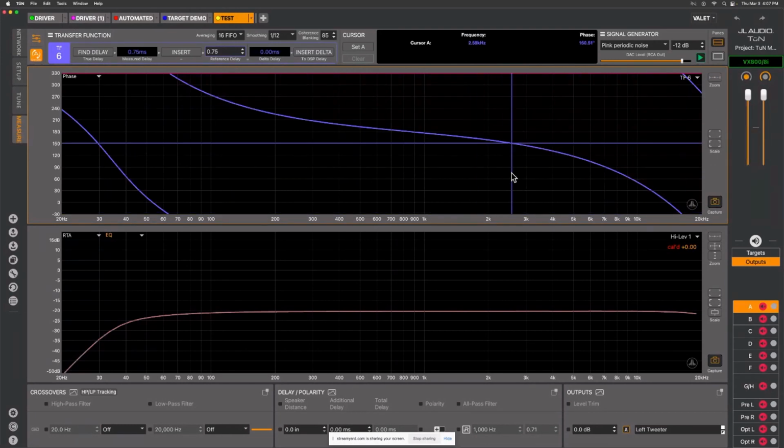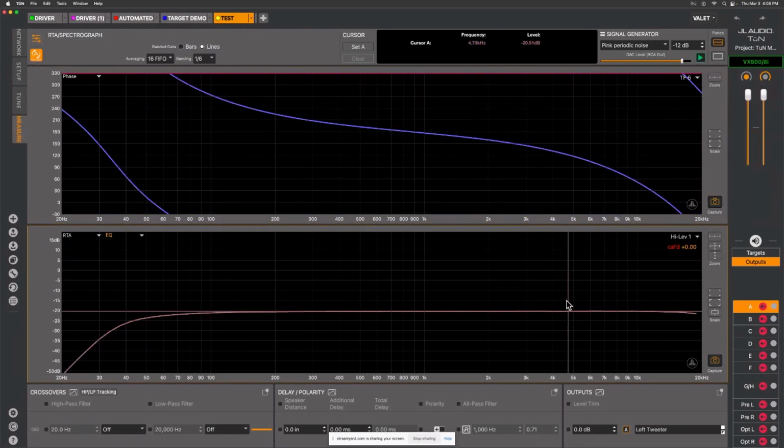So as a reminder on time-based measurements, phase is a time-based measurement, and as a pretty smart guy said once a long time ago, time is relative, so therefore phase is relative. By setting the reference delay, we're creating that relative measurement. So as Matt said, now the phase data actually makes sense because we know when the time is starting, and ultimately we know when things are arriving.